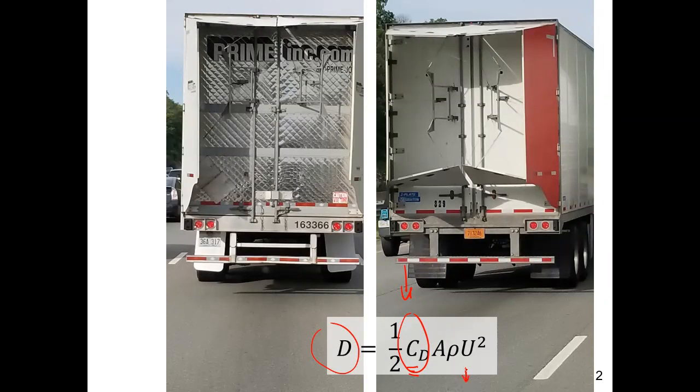If you can decrease the drag force, since the power is a constant, if you can decrease the drag coefficient in order to have no change in the power that this truck can use to go down the road, necessarily the velocity would increase as the drag coefficient goes down. So that's the whole idea. And you'll also see those spoilers on the cab, and you'll also see them on the side underneath the truck, and they're all to reduce drag coefficient.